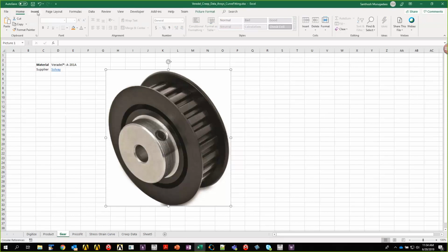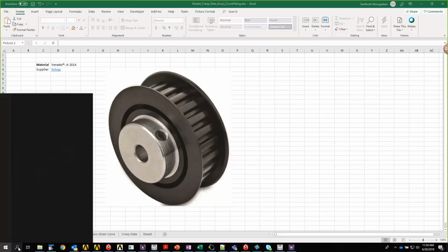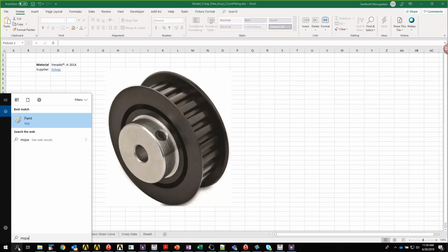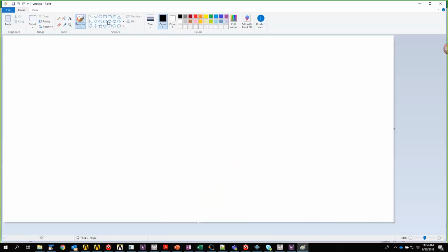So when you are doing this process, if you want to understand the torque, basically there is a material here and there is an interference fit. Because of the interference fit, a contact pressure gets established at the interference.